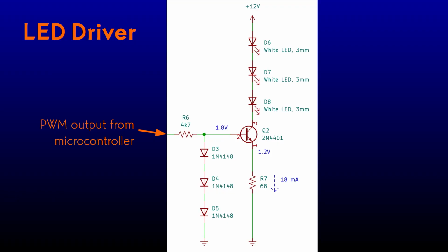On the breadboard, I'm using a little PWM circuit built from a 555 timer. I'll put the schematic on the project GitHub and link in the video description. The schematic shows a log taper pot for the pulse width adjustment, because the human eye's response to light is nearly logarithmic, and a log taper gives us a usable range of perceived brightness.